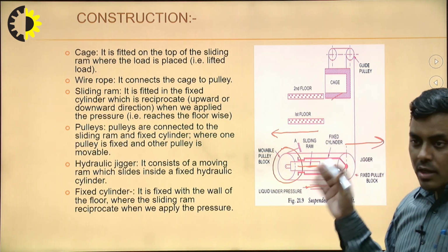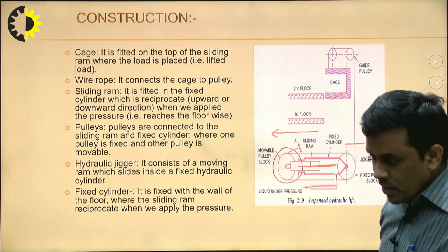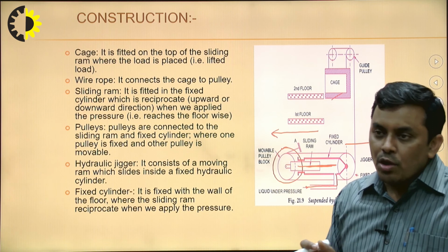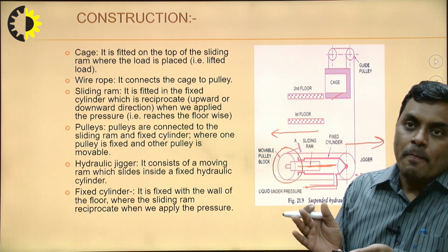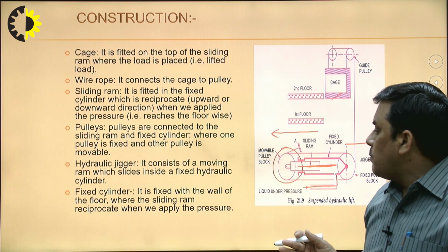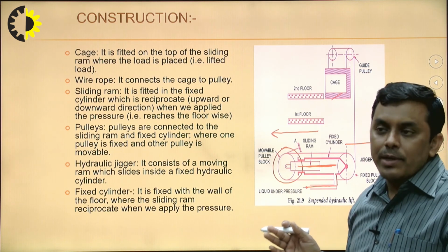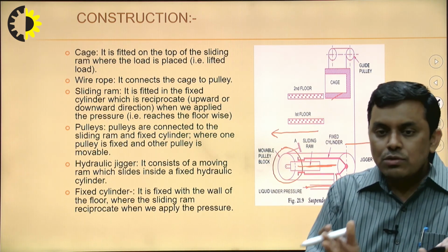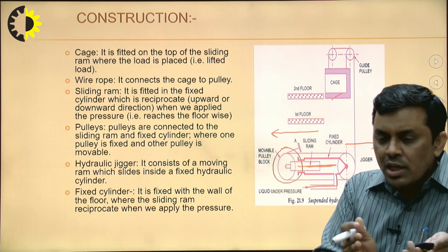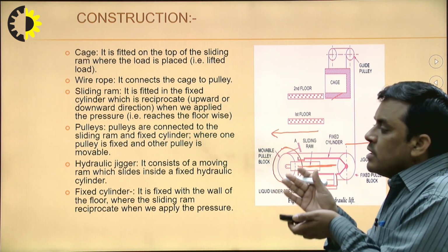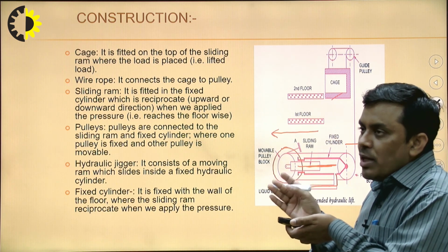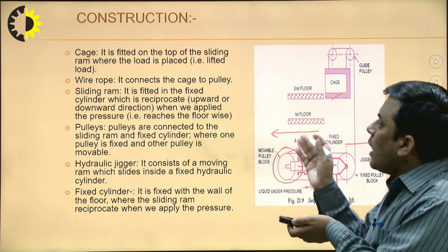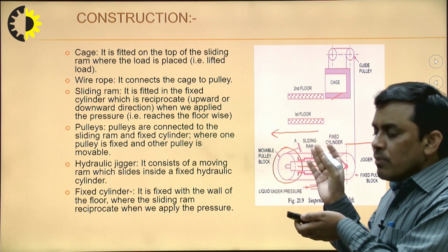So here we can understand, at least after watching this particular video, what functions we can perform with the help of high pressure fluid. We can perform many functions with the help of this very smoothly, without any vibrations, without any noise. That's why we need pumps to maintain a certain pressure, and to store the extra energy of the pump, we need arrangements like a hydraulic accumulator, through which the energy can be supplied to the hydraulic lift or hydraulic press type of arrangement.